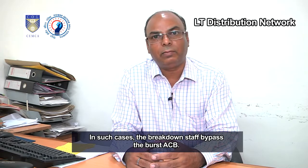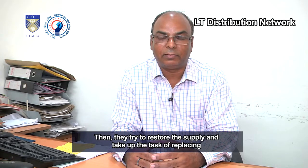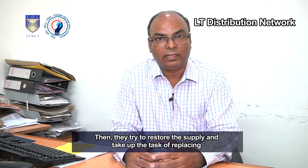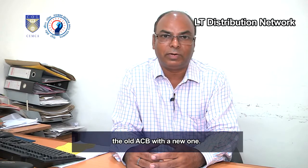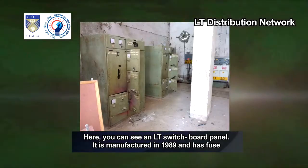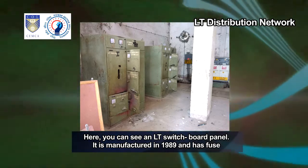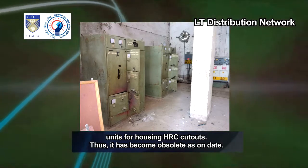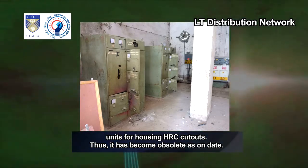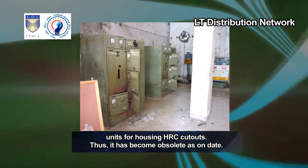In such cases, the breakdown staff bypass the burst ACB. Then, they try to restore the supply and take up the task of replacing the old ACB with a new one. Here, you can see an LT switchboard panel. It was manufactured in 1989 and has fuse units for housing HRC cutouts. Thus, it has become obsolete as of date.